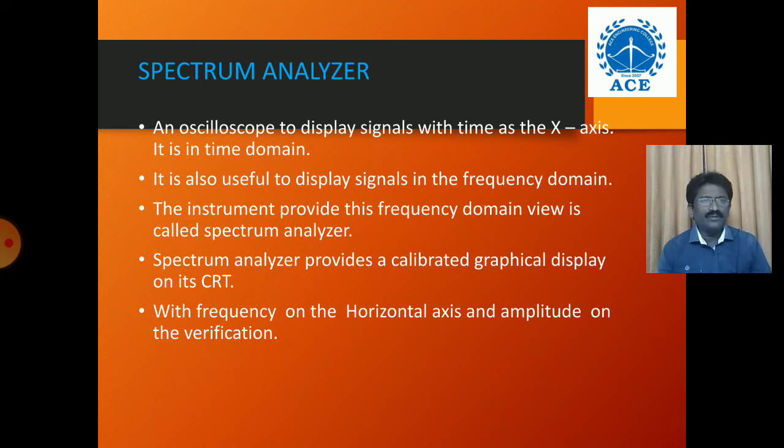With the help of the tuning circuit, you can vary the fundamental frequency. That means with the LC circuit we can tune the frequency, because the LC circuit acts as a tuning circuit.